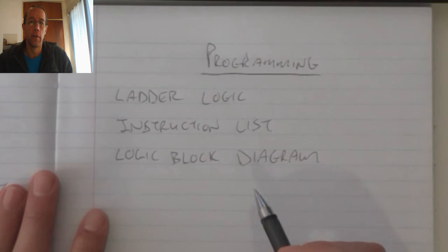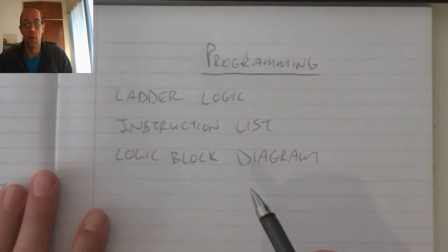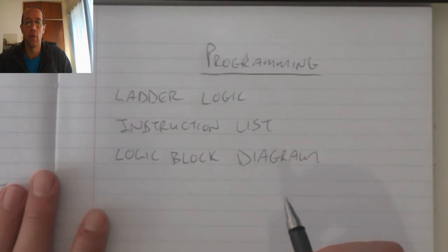Some PLCs actually do have buttons and a display unit on the PLC itself, which allows for simple tweaking or minor alterations to a program, for example setting the time or changing a normal open input into a normal closed input.